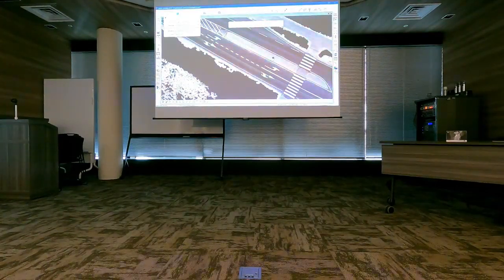And I do a mouse click, which is about the center point of a bounding box for the paint marking, and then the software finds which paint marking symbol matches what we have in the intensity in the point cloud, which one matches the best, and places the polygon as it is defined in my TerraScan settings, so it places a library polygon for the paint marking.